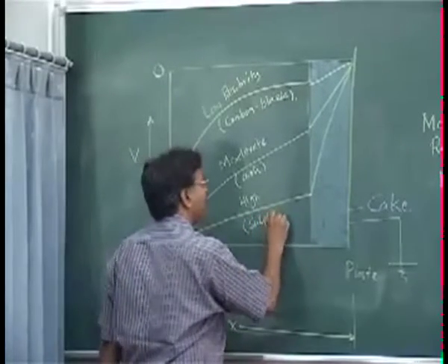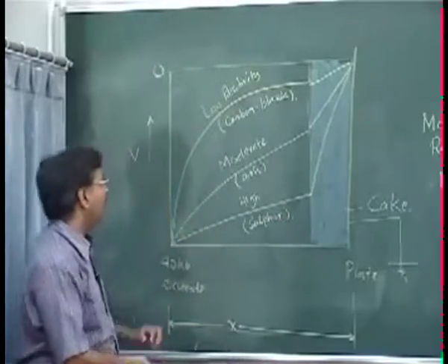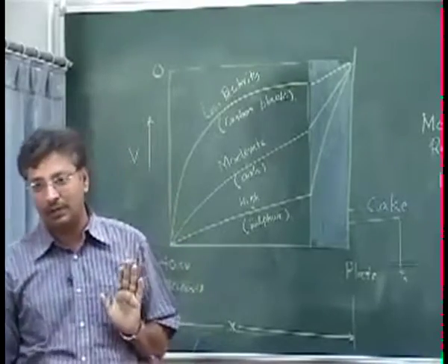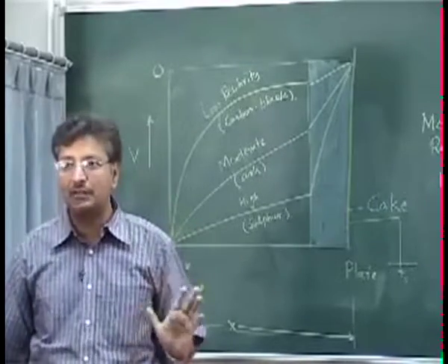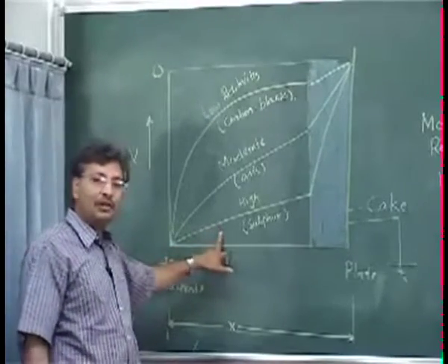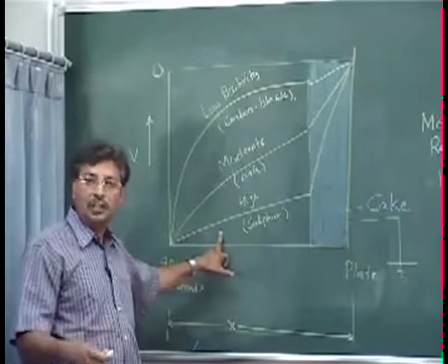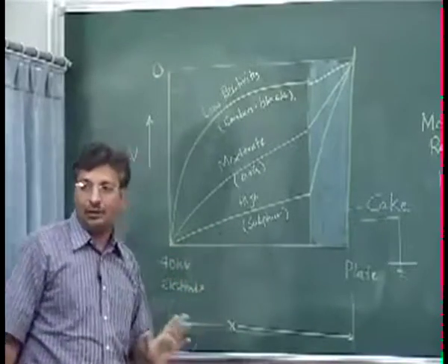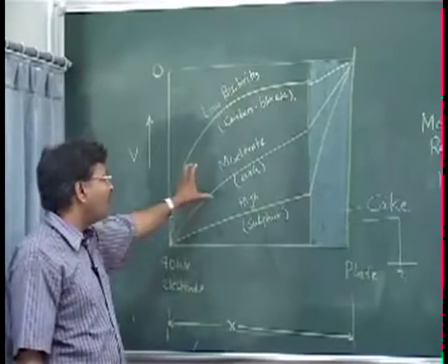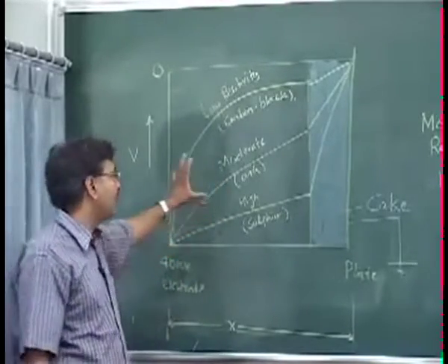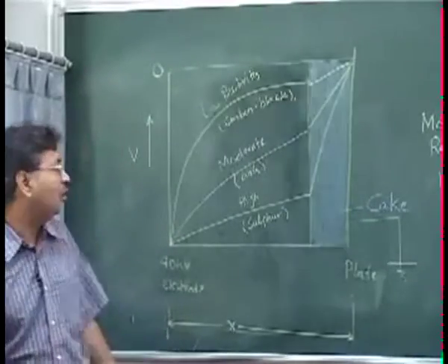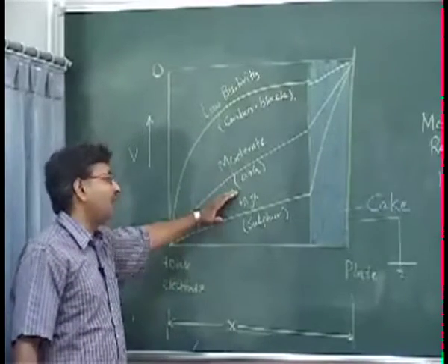It's just extreme examples that I am giving you. If you are dealing with carbon black, you go to the carbon black industry, they will not talk to you about ESP. They will talk about bag filters, which we have not talked about. In other cases, for example if sulfur is there in your ore or in your process, they'll say, well, we are not going to use this one. So for ash or ash-like substances, it works very well. But unfortunately, Indian ash has a low resistivity, so that will fall somewhere in between.